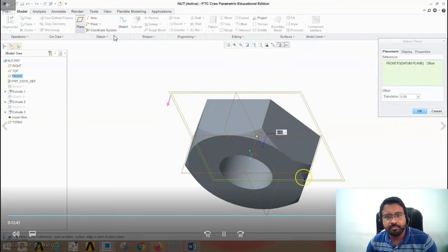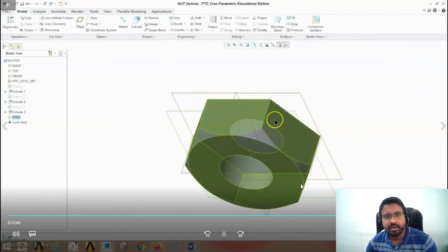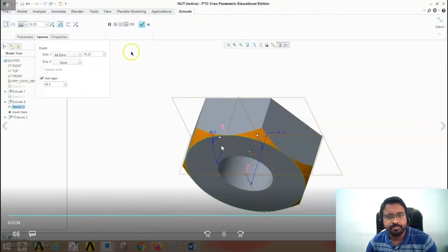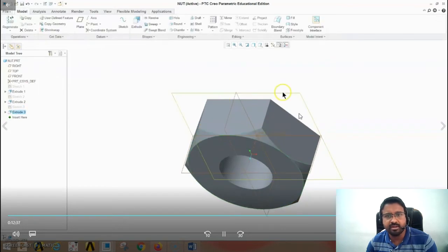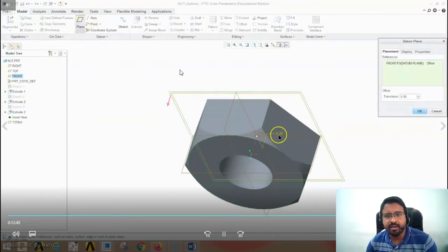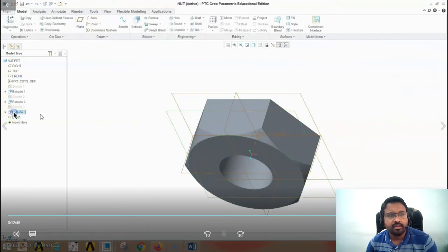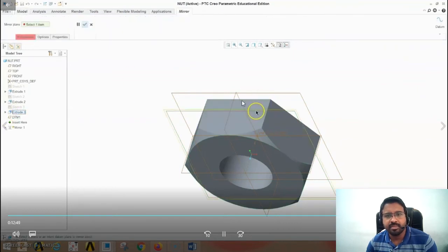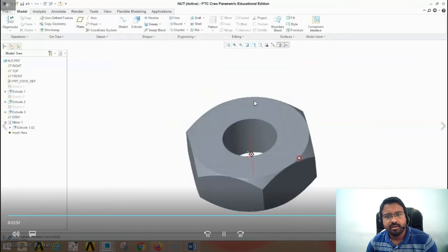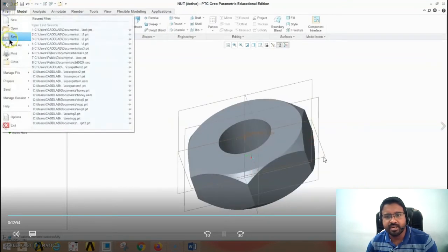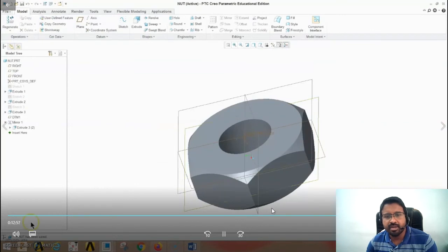You can repeat this on the other plane. You can see here how the same can be transformed to the other side. The same procedure can be applied to the other side, mirrored. That is the plane. We check this plane and then go to extrude part and then mirror it. So mirror with the center plane. With the center plane as a reference, we mirror this, and automatically it will be mirrored to this side. So keep the center plane as a reference so that the trimming that you have done on one side will be trimmed on the other side also.